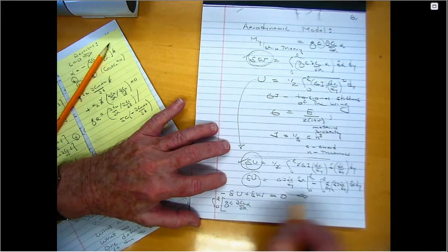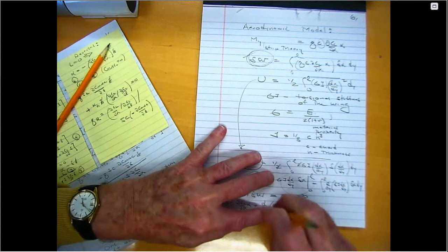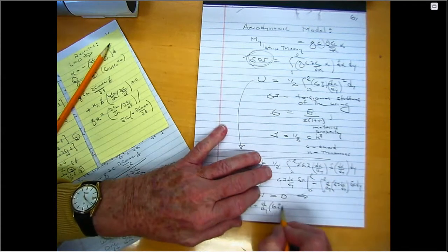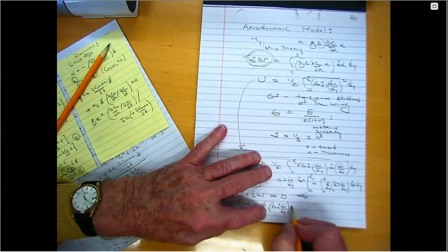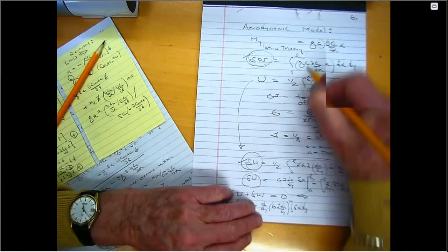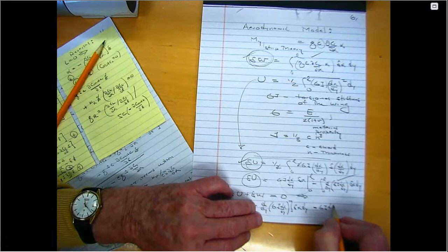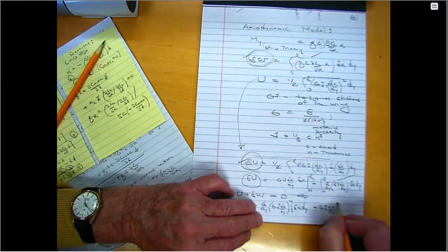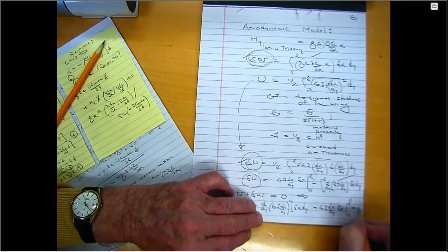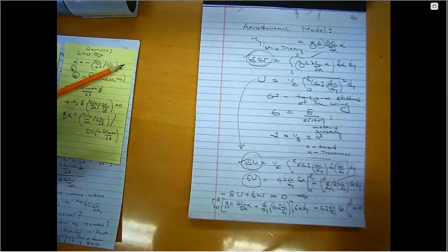But it's minus del U, and here's a minus sign, here's a plus sign, plus d/dy of GJ d alpha/dy, all multiplied by del alpha dy. So I'm taking care of this term, I'm taking care of this term, and then I have minus GJ d alpha/dy times del alpha evaluated at the two limits. That's equal to 0. So now I'm done for the moment writing the equation.